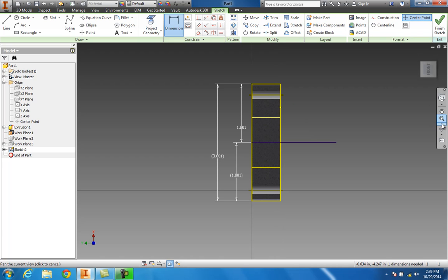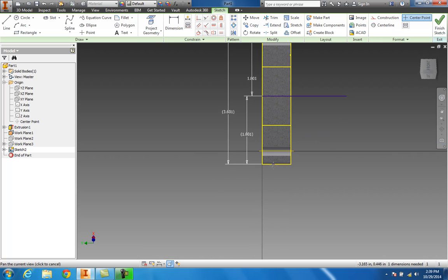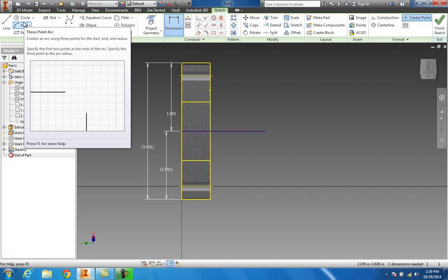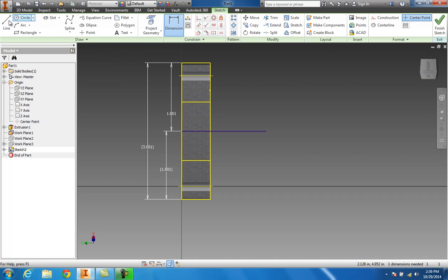Again, I want to look at this thing where I can look at it flat. So make sure you're on your right work plane, and tilt it up so I can see it, and I'm going to start drawing this thing. It looks like the width of this is 1.5, so I'm just going to draw a line right here, draw it up so far, and I want to draw another line right in here.